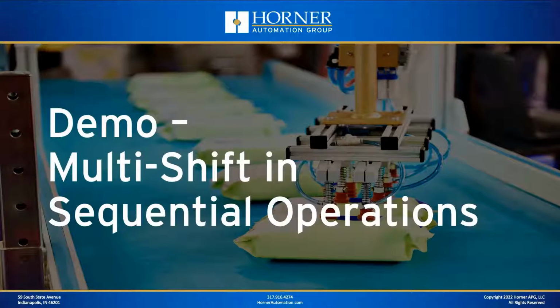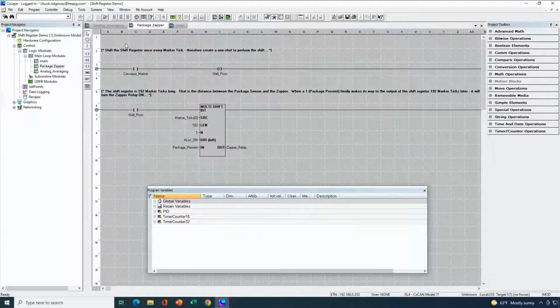So now let's go ahead and fire up Cscape and take a look at what's happening with our program here. I have configured Cscape for this application I just described, and really the operation to do all the shifting is going to be performed in just a couple of rungs, so pretty straightforward. The input to a shift register, basically whenever that input is on, the shift register is going to perform a shift. So it's actually going to shift as it's been specified.